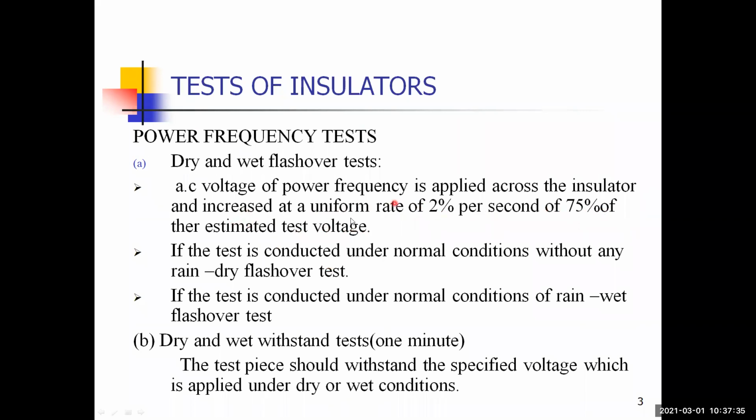AC power frequency. If the test is conducted under normal conditions without any rain, it is the dry flashover test. If the test is conducted under normal conditions with rain, it is the wet flashover test. So we have to check the insulator is working properly with and without rain: without any rain, the dry flashover test, and with rain, the wet flashover test.